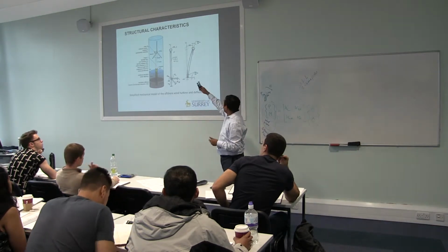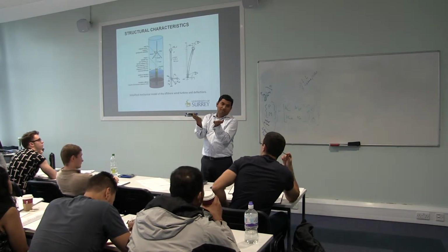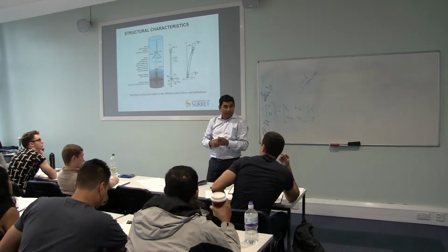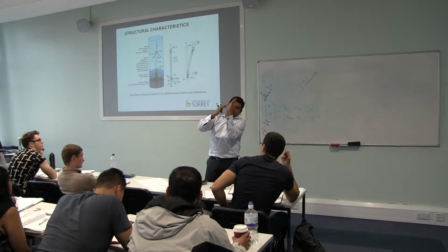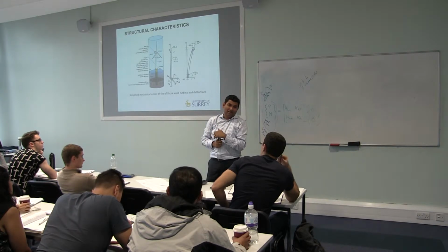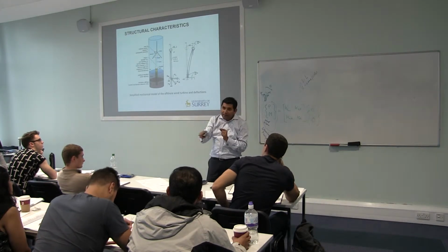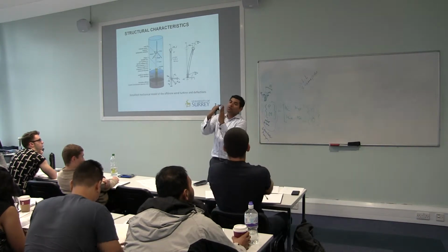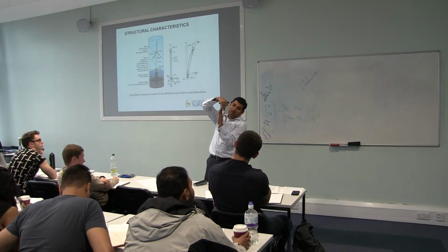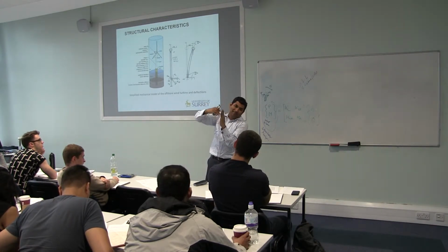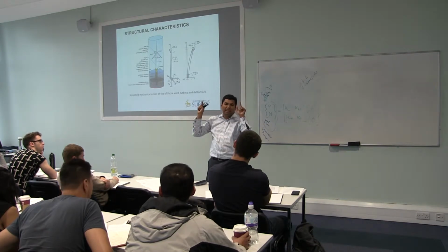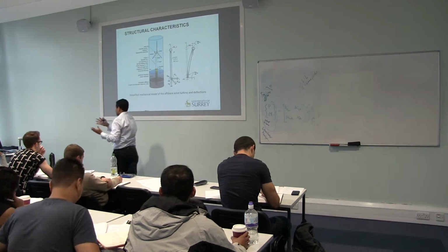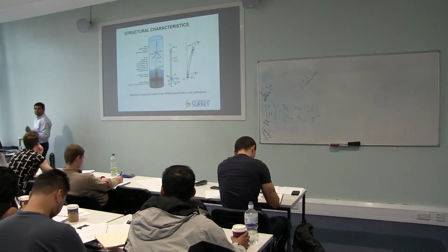Because if it tilts more, think of the gearbox, there can be faster wear and tear of the gear. If it tilts more, the blades may hit the tower. If it tilts more, the cooling fluid inside can't circulate properly. If it tilts more, the mass acts as an eccentric weight, and you get a lot more movement on the foundation. So roughly half a degree is allowed till now, but they want to increase it, but it's under discussion.